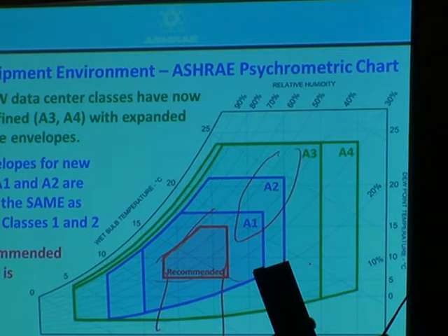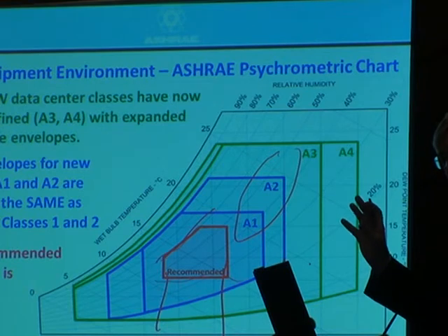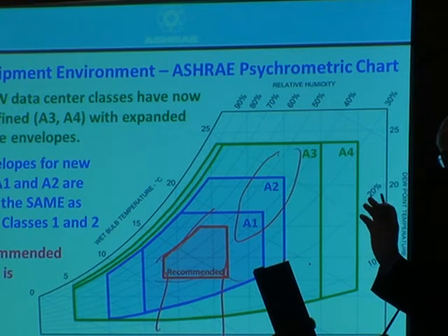And again, if it's 37 in the summer, and you have 35-degree equipment in your data center, you can't just blow outside air into your data center. It's not cool enough. So you've got to do some refrigeration or some cooling, right? But in the winter, you ought to be able to use the outside air much to your advantage and turn off air conditioning equipment.